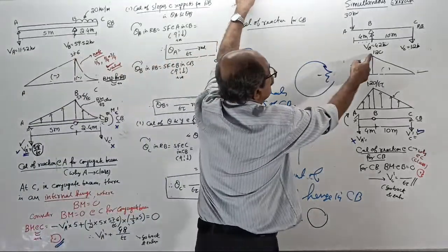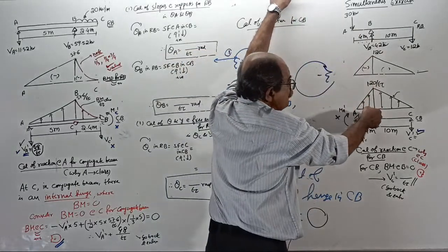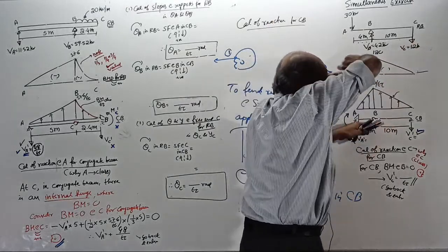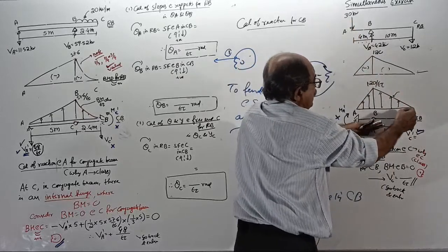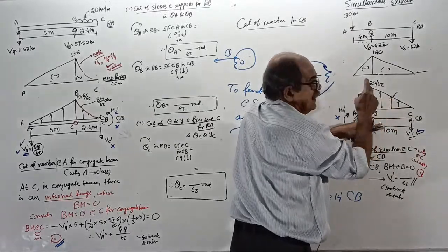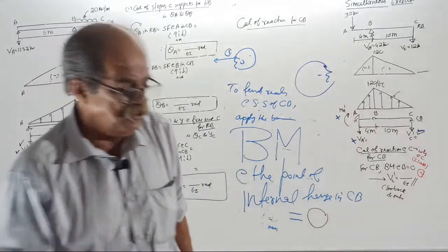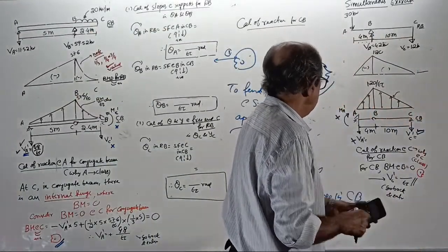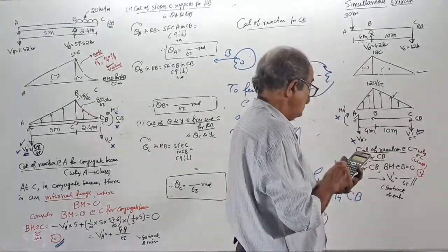Okay, come to this question. I will dictate here. You should write. Bending moment at B equal to 0, look that side. Minus VC dash into 10 plus half into 10 into 120 by EI into 1/3 of 10 equal to 0. You get the value of VC dash there. I will write the answer. See, I wrote, look that side. Just a couple, 120. Okay.